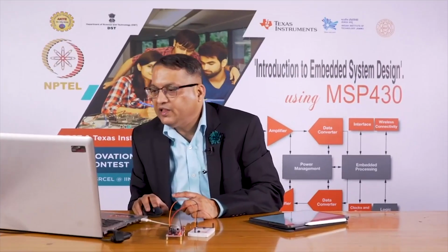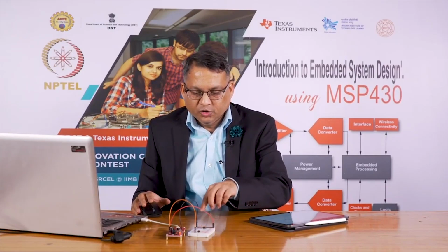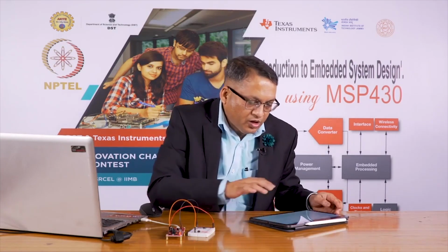In that, you are again waiting for the switch to be released, because you pressed it. Usually human interaction means you are going to press the switch for a much longer duration, and so this will hold the state of that pin at 0. You are waiting for that to be released. That is the second instruction.